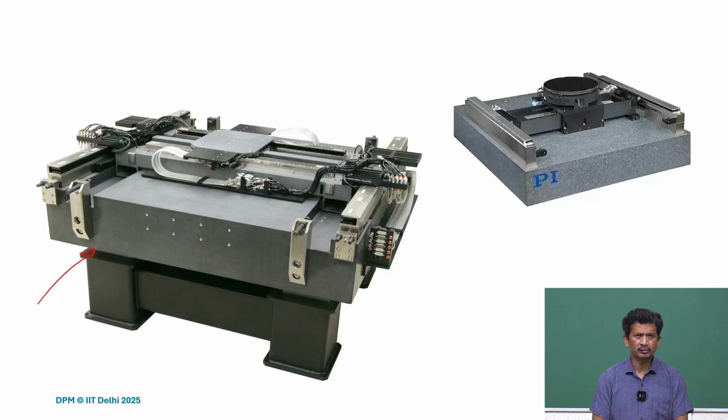So this is widely used, and you can see the linear motors here for this direction, and you can have the same way here as well. So here you see again no contact because it's supported on air bearings. So you hardly see any kind of guides. It's guided by this surface and the surface opposite to that, on air bearings.